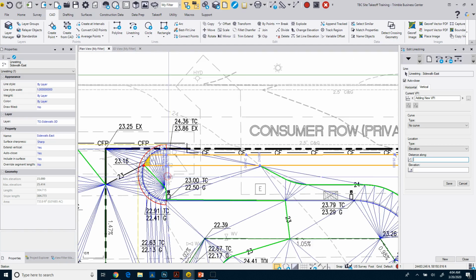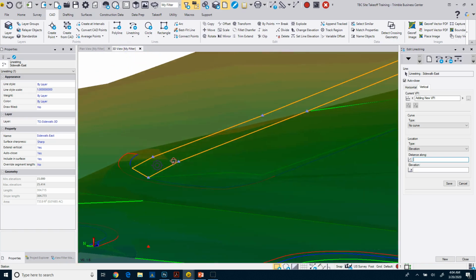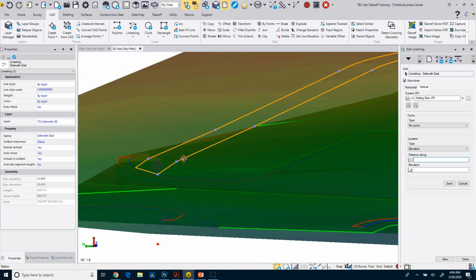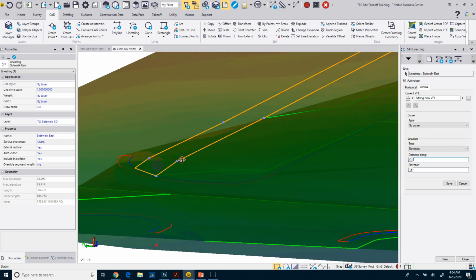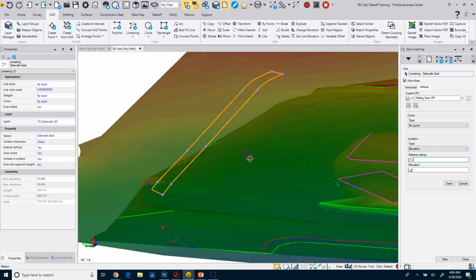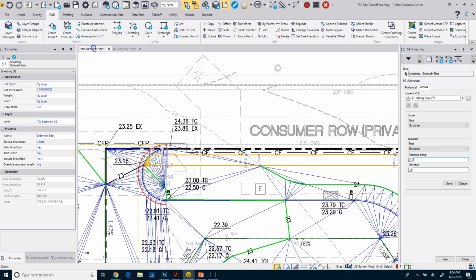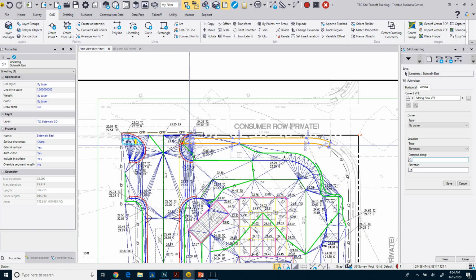And then I've got my sidewalk in there. So if I look at it, I can see here that I've got my ramp, I've got my sidewalk, and it's all tying in. Okay. So again, might be a little bit more detailed than needed, but what's going to happen is when I use this sidewalk, it's going to pull my proposed surface out to this area over here. Okay.